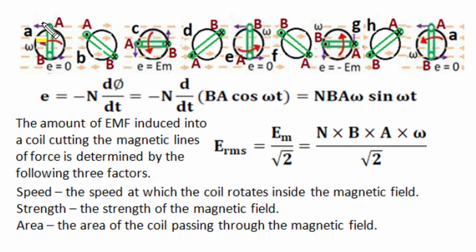As this rectangle coil loop rotates in the anti-clockwise direction with constant angular velocity, the angle between the magnetic induction vector and the area vector is a linear function of time, omega t. The cosine of that angle results in time varying flux linkages with the rectangle loop, and as per negation of the rate of change of flux linkages, E is equal to minus n d phi by dt.